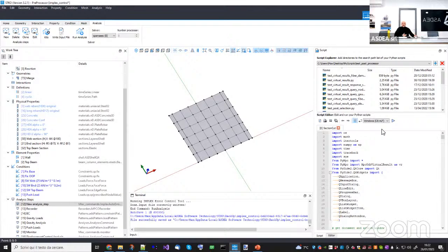Yeah, there are many. The first one is that now you have more flexibility in defining the tensile and compressive behavior. That is an advantage for modeling a broader class of concrete. The other thing is that we made two main changes to the theory of the constitutive model to avoid the premature failure we had with the damaged TC3D. One of them is the anisotropy of the crack internal variables that I told you. The other one is a little more difficult to explain.